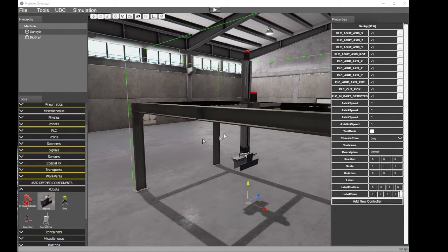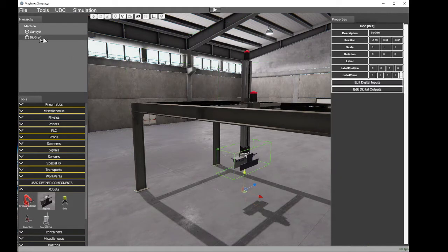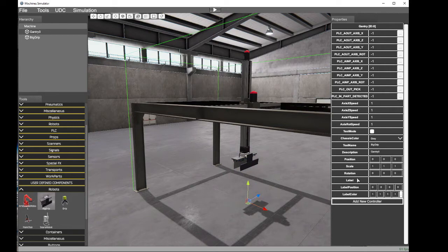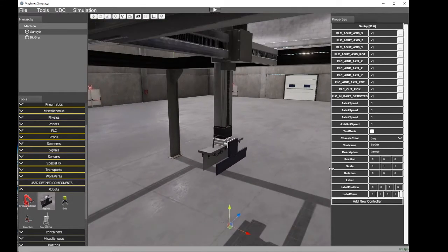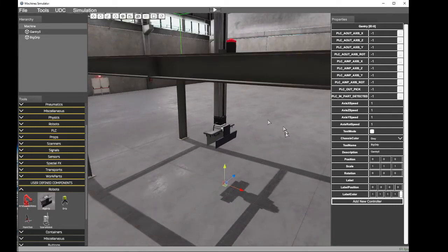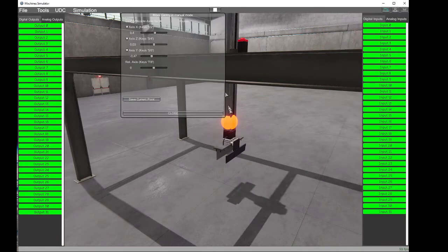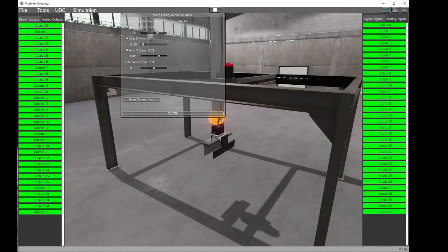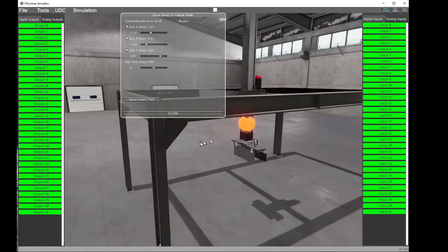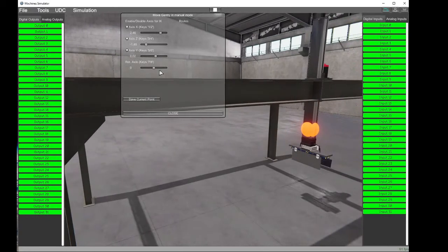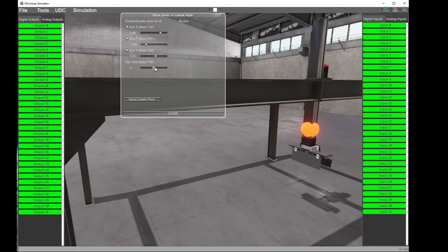To move the grip with the gantry, I must select the gantry, and in tool name, I must write the name of the element that we want to work as the gantry tool. I named the grip big grip, so in the tool name I write big grip. In this way, the system will treat this component as a child of the gantry tool. Now, if I press test mode and play, see how this grip that we have chosen as the tool of the gantry moves together with the gantry.